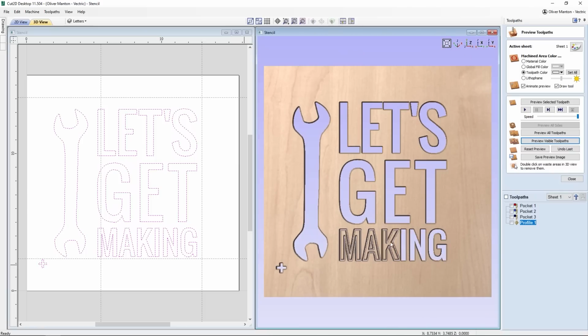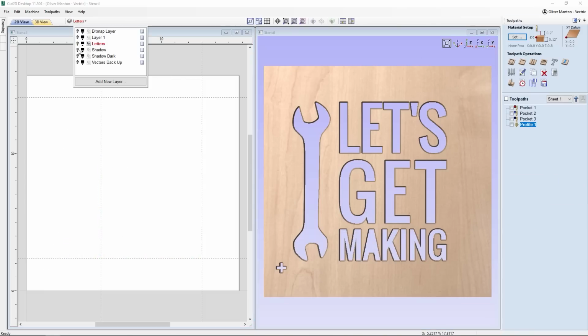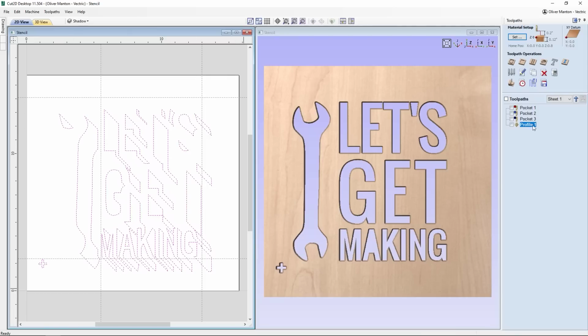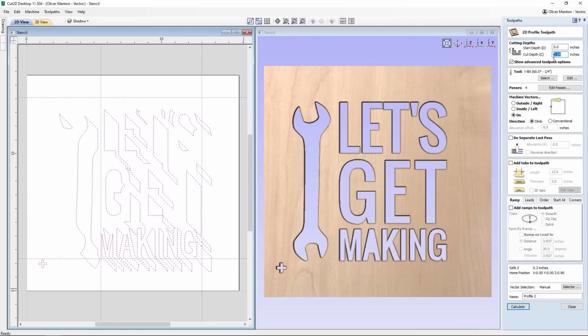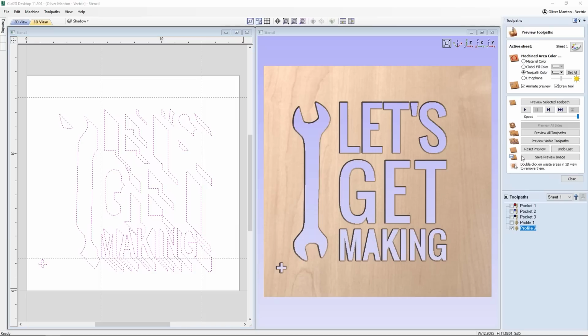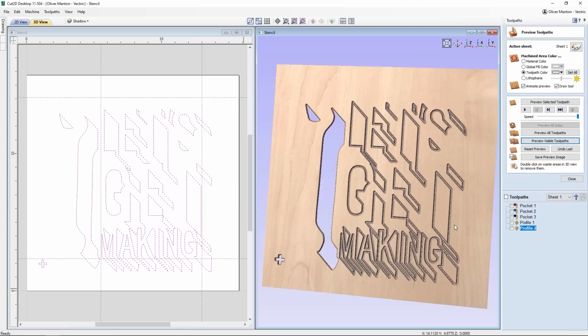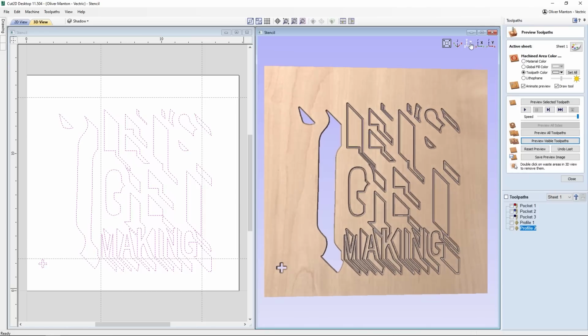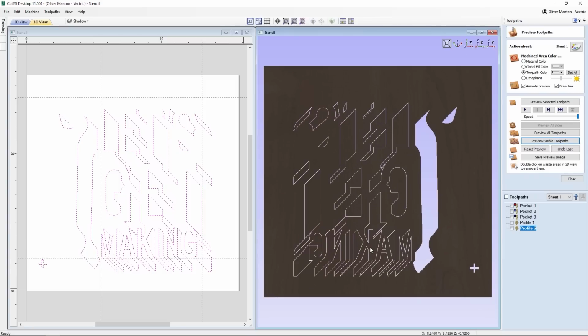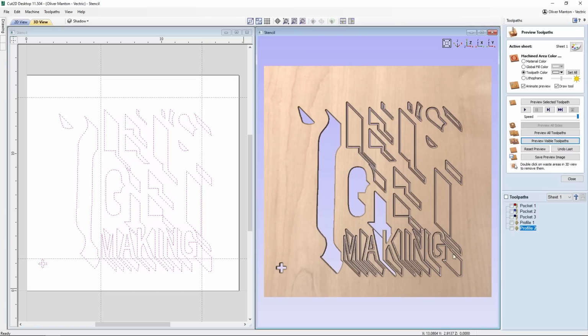So that's the first sheet done, on to the next 2. For the next 2 sheets it'll be the same process, selecting the vectors we want to cut on the line and with the V-bit. Handy way I found to see if all the vectors had come through properly was by clicking the Z and holding down the Shift key, which will actually flip it or do the opposite of what it normally does. This works on all the X, Y and Z axes as well.